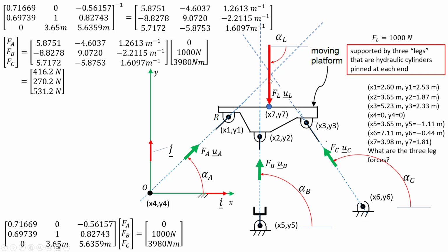If it had a 0 area, that means that the B would have also passed through that line of intersection, and that would have meant that you couldn't solve for the 3 loads. So you need to have that triangle there. It is very cool and related that the matrix is invertible if and only if the area of this triangle is non-zero.